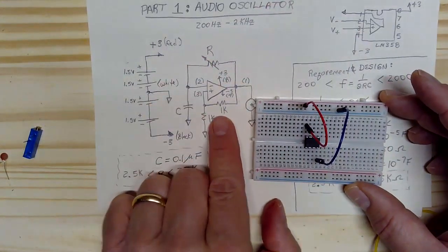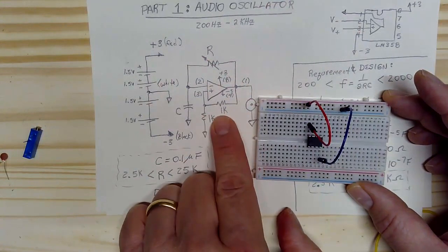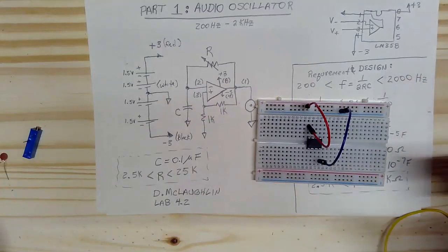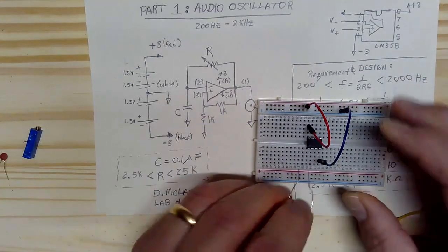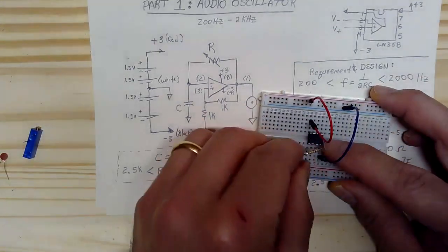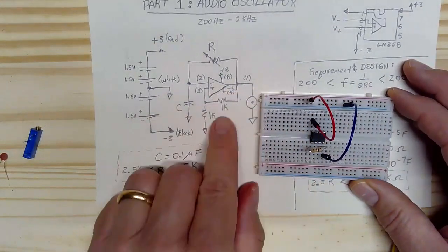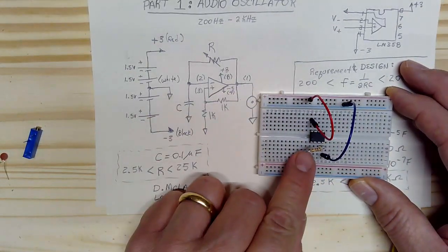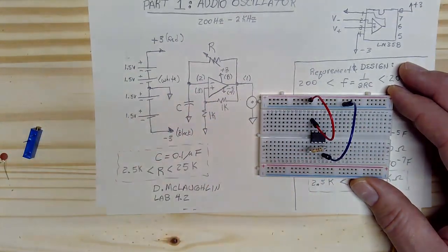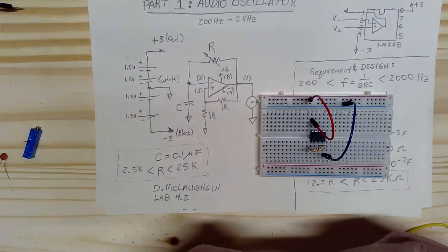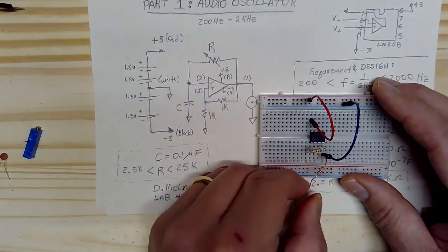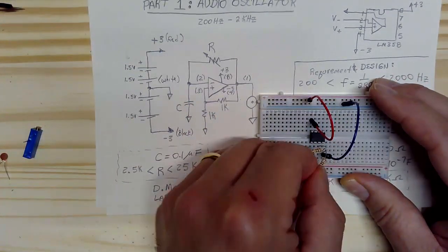Okay, now I'm going to just work on these two 1K resistors. So you'll see that between pin 1 and pin 3, I have a 1K resistor. I'm just going to tuck that right into there, between pin 1 and pin 3. That's this resistor right here, pin 1 to pin 3. And then from pin 3 to ground, I have another 1K resistor. So pin 1, 2, 3, I have this resistor, and then that's going to go to our ground.